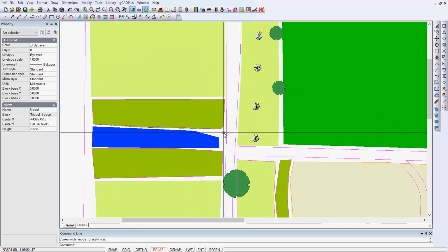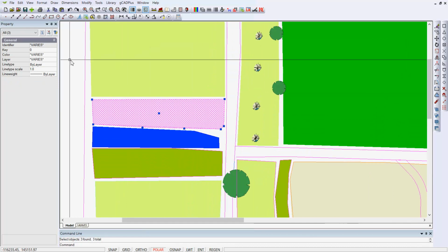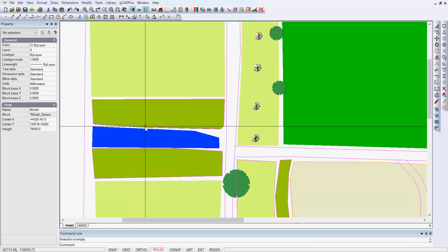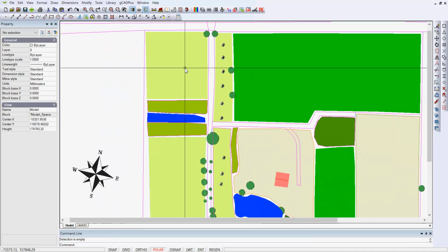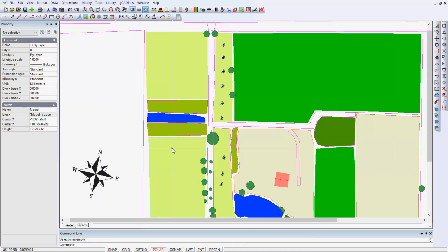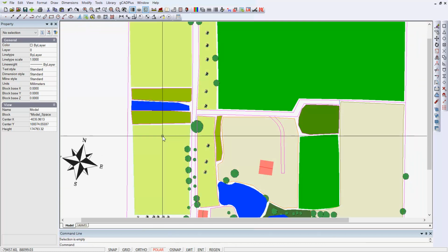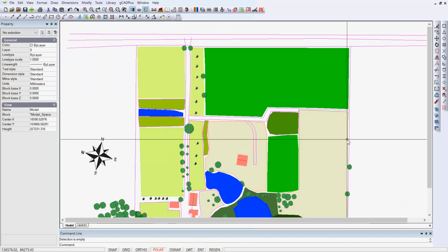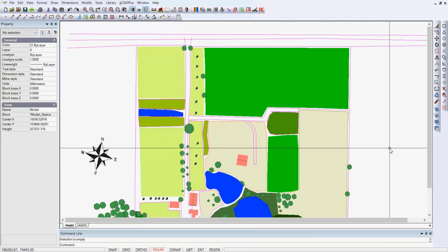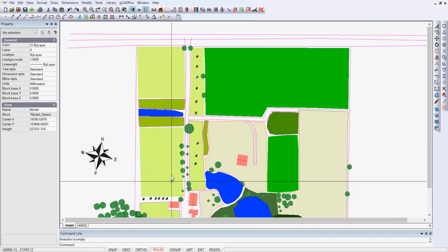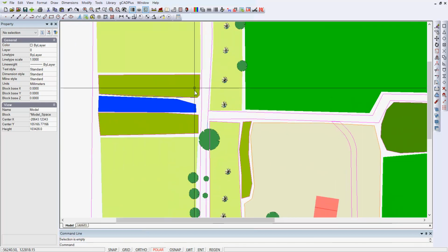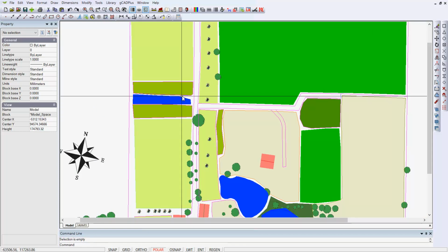Now I imagine that down here we've probably got a similar situation. Again, we've got 2 polylines and a hatch. So I'll spend some time just going through the drawing, making sure that these zones, which represent fields or paddocks of different uses, and that's a reminder that we're going to need some sort of legend here. Just see if we can simplify things. There seems to be a bit of a mismatch of colour, maybe, and of layer as well. So we'll carry on, just cleaning up a little.